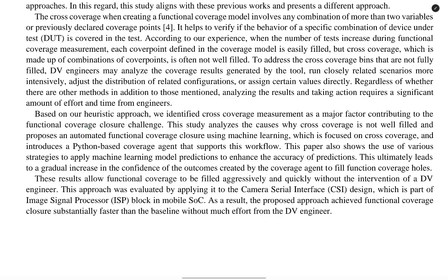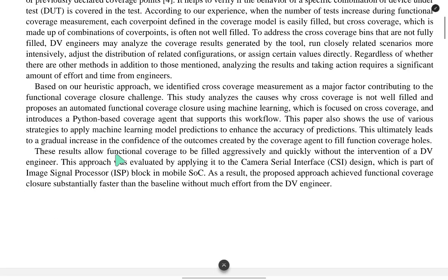This study analyzed the causes why cross coverage is not well filled and proposed an automated functional coverage closure using machine learning, which is focused on cross coverage, and introduced a Python-based coverage agent that supports this workflow. This paper also showed the use of various strategies to apply machine learning model prediction to enhance the accuracy of prediction. This ultimately leads to a gradual increase in the confidence of the outcomes created by the coverage agent to fill functional coverage holes. These results allow the functional coverage to fill aggressively and quickly without the intervention of the DV